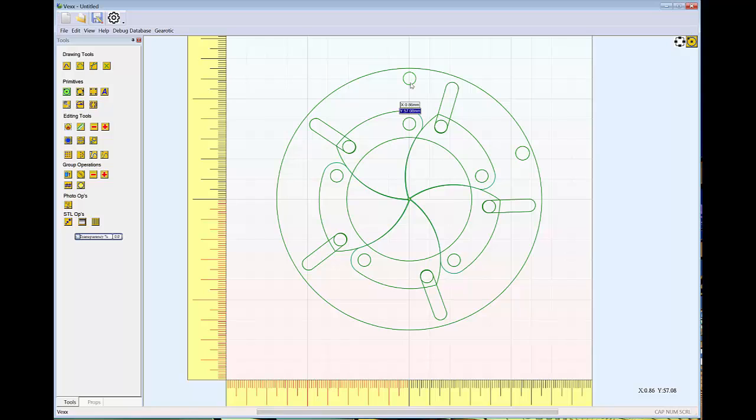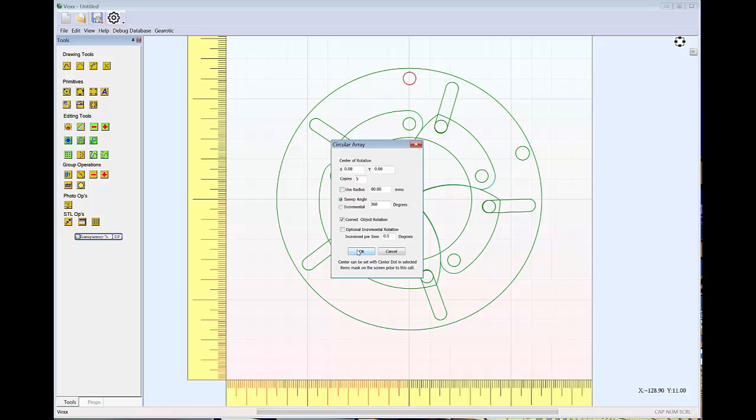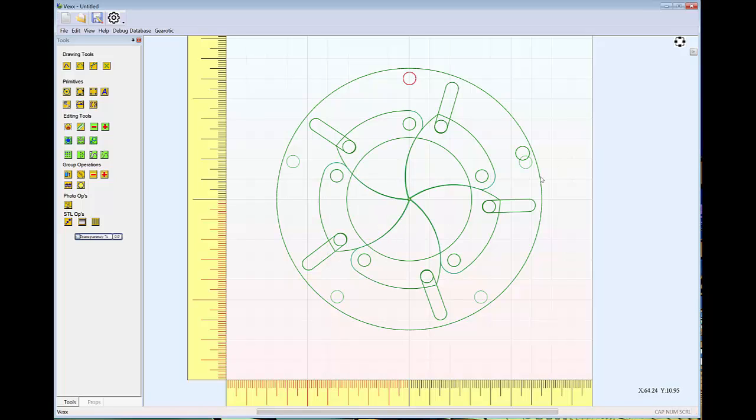6.25. We'll copy this ring on an array copy 5 times. Now if you're not going to use this timing ring for a pin, I am going to use it, so I'm going to retain that and remove this 5th one so it's not in my way, and I'll support my ring only on 4 points. So these 4 points we will group together on their own.